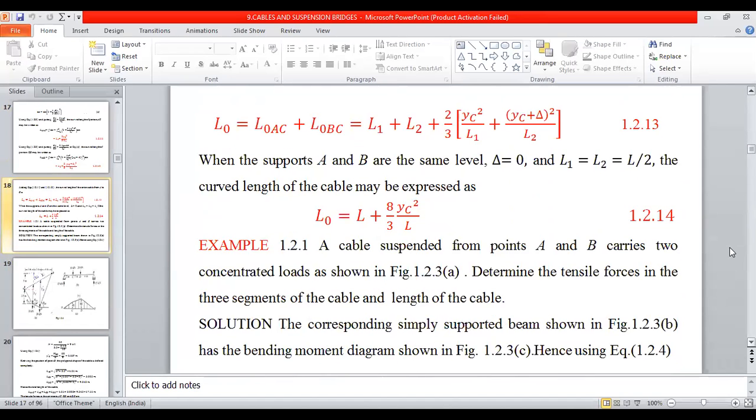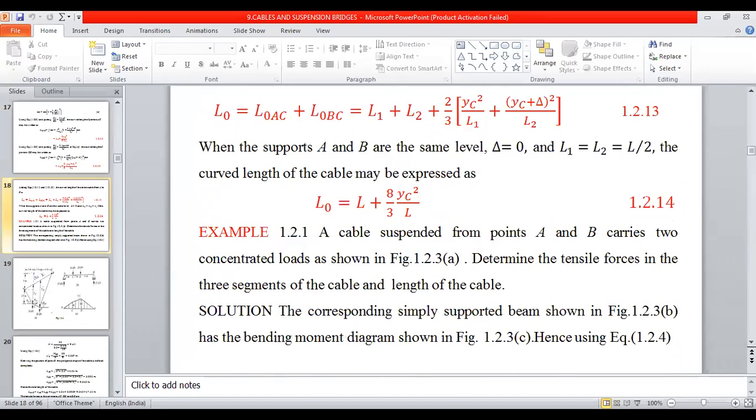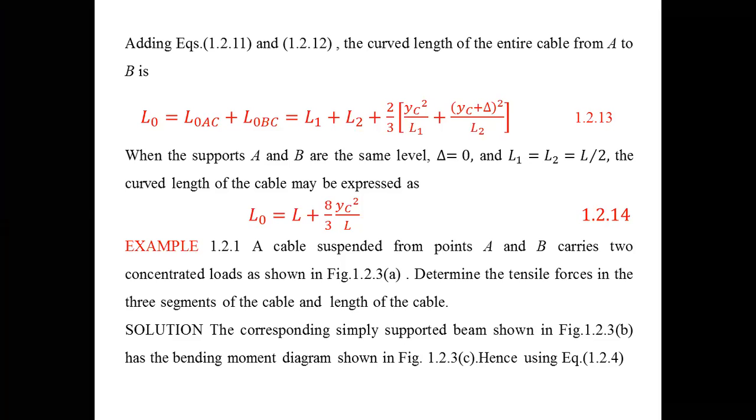Yeah, this is the example. A cable is suspended from points A and B, and carries two concentrated loads as shown in the figure. Determine the tensile force in the three segments of the cable and also find the length of the cable.